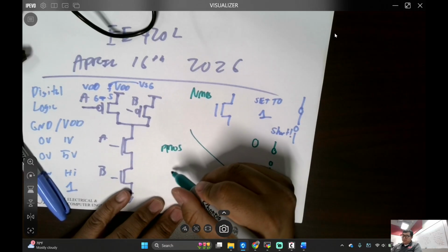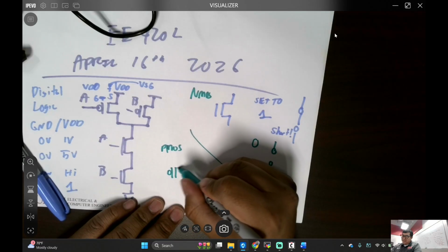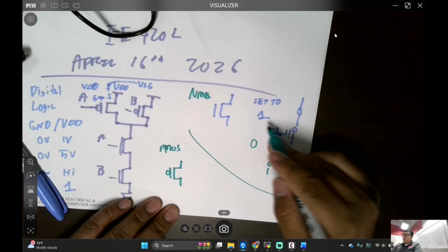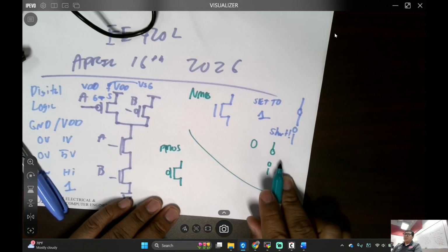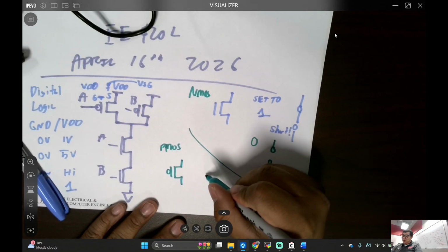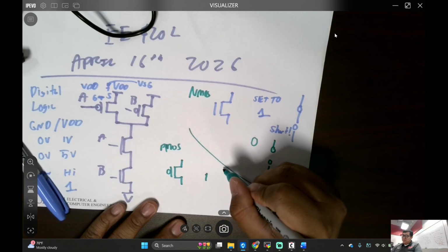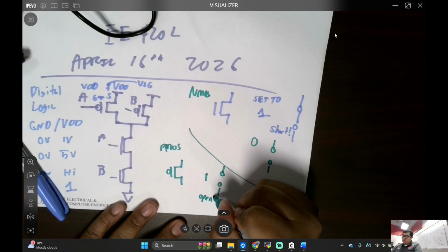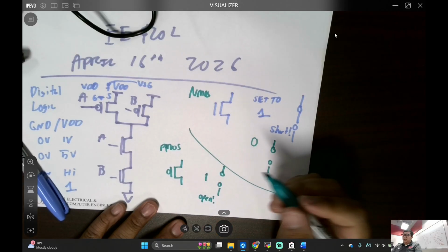Okay, right? Looks like this little bad dude. There you go, right? So for the NMOS, 1 makes it a short, 0 makes it an open, right? What does that mean for the PMOS? Everything's kind of upside down, right? So if I were to set a 1, right, it's going to be an open, right? 1 volt at the gate.